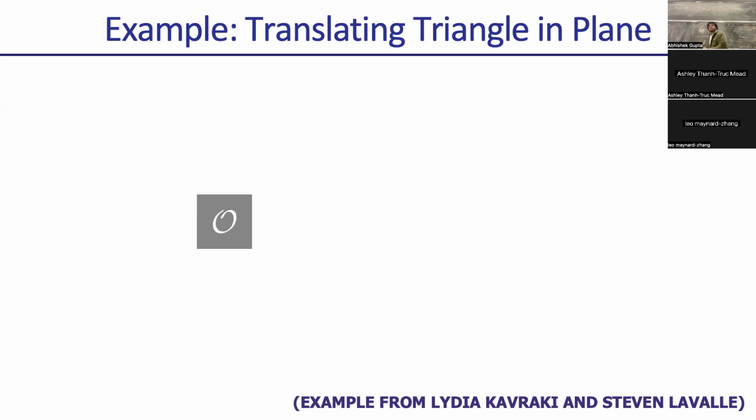This is the robot. So when the robot is at this X, Y, this point is colliding with the obstacle. Hence, this point has to belong to configuration space, or this point has to belong to a configuration space obstacle. So you can kind of think of it that way. And similarly, when you move the robot over, it's here. Again, a point is colliding with the obstacle, so this point has to belong in the configuration space. And now when you bring the robot down here, you can see this point is colliding, and so this point has to lie in the configuration space obstacle.